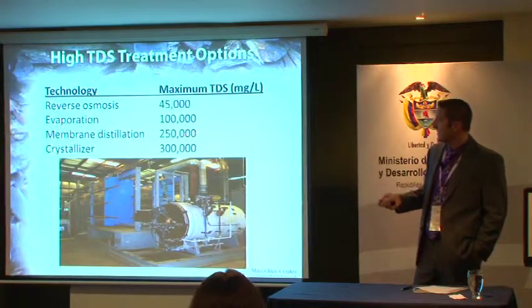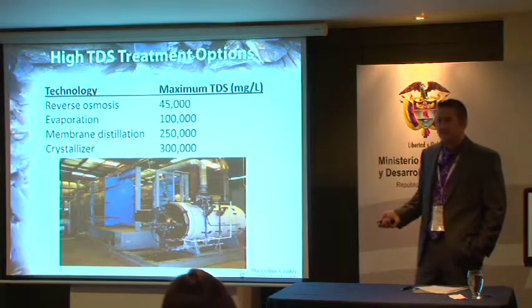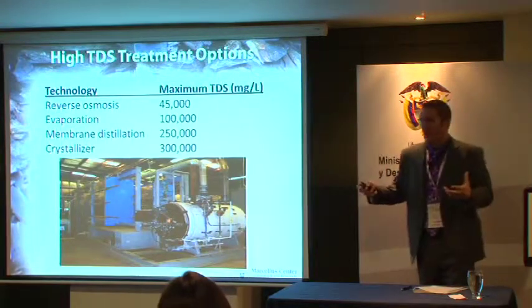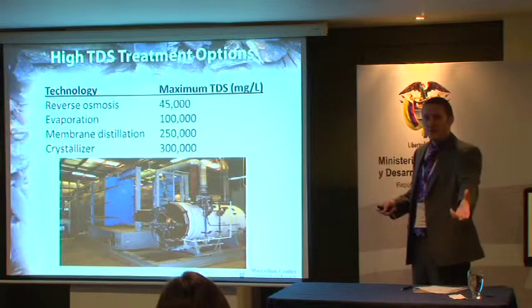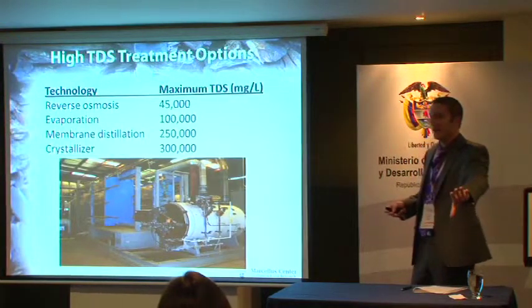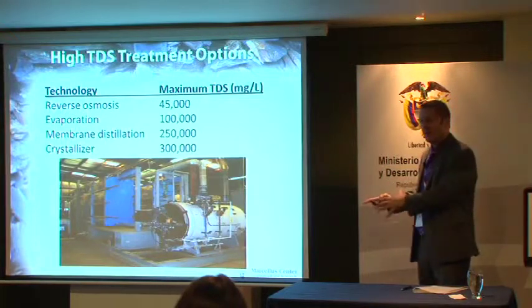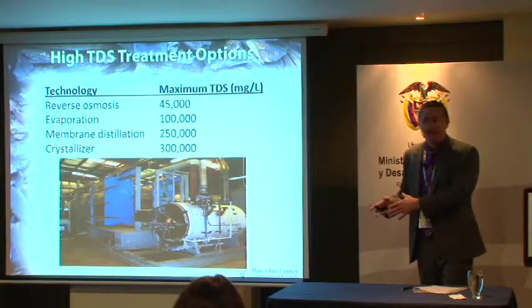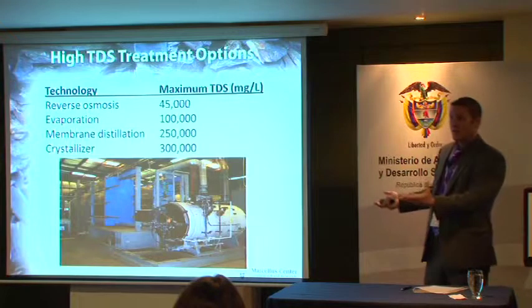There are evaporators. That's actually what this unit is. It, in essence, boils the water, and then that steam stream is recondensed, and that water can be recycled, and then you end up with a briny concentrate, and typically that's going to go to the injection wells and not get recycled.